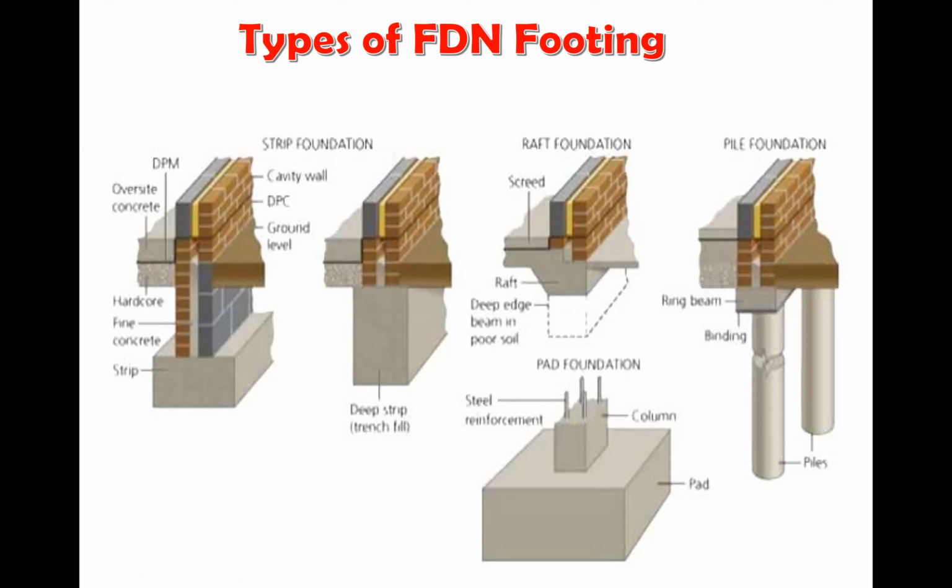So what you don't want is to use a narrow strip foundation in a soil like that, where there is always some kind of movement. The area that is holding against the soil on the side is not enough friction to hold up, even though it's holding underneath. You need some forces acting against the side here. With a deep strip, you have more surface area for the soil to act as friction against the side of the footing.